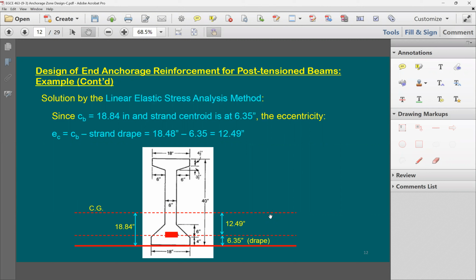In your midterm example? When I have 4 here, I'm just assuming them to be at one location. But it's important that when I detail the beam for my design, I put them so that the centroid or resultant of these 4 strands is right at the location, so that e is the same as I have considered in my analysis.